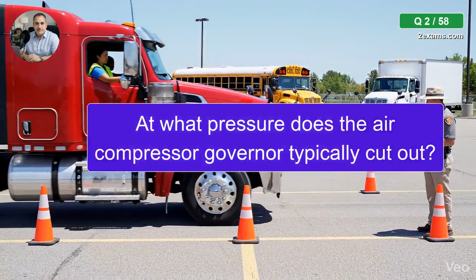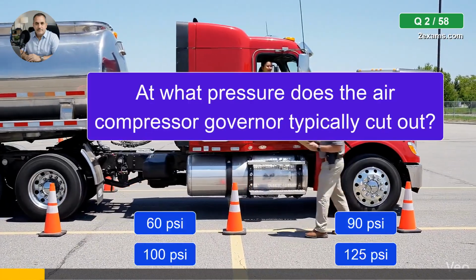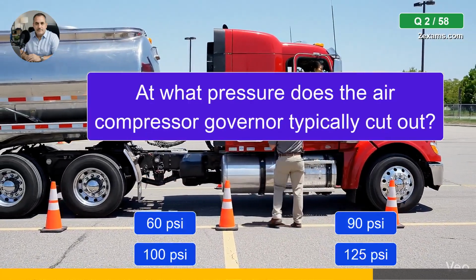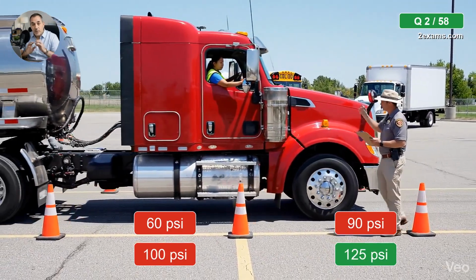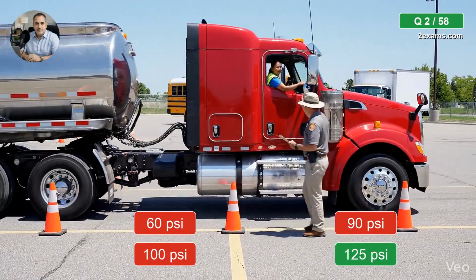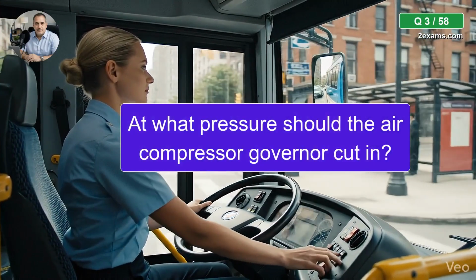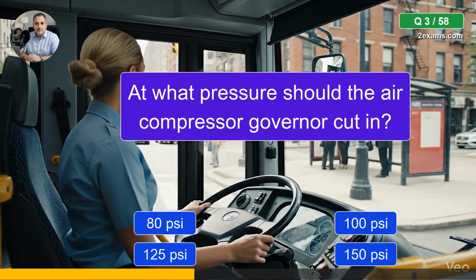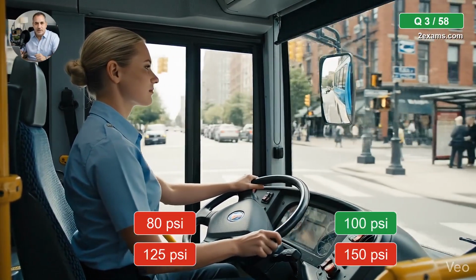At what pressure does the air compressor governor typically cut out? The correct answer is 125 psi. At what pressure should the air compressor governor cut in? The correct answer is 100 psi.